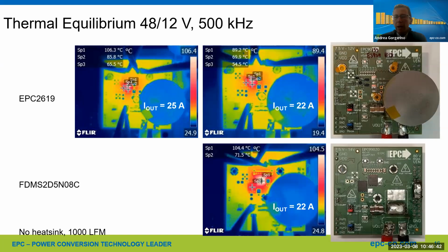There are, I would say, 2 ways. First of all, there's a growing list of dedicated gate drivers for GaN, which not only take care of controlling that gate drive voltage, but are also very strong in terms of the dV/dt they can survive, because that's the thing: you use GaN because you want to go fast. You want to make sure your gate driver, which will see that voltage transient on the switch node, is able to withstand that. So there's a growing ecosystem of gate drivers and controllers specifically tailored for GaN devices.